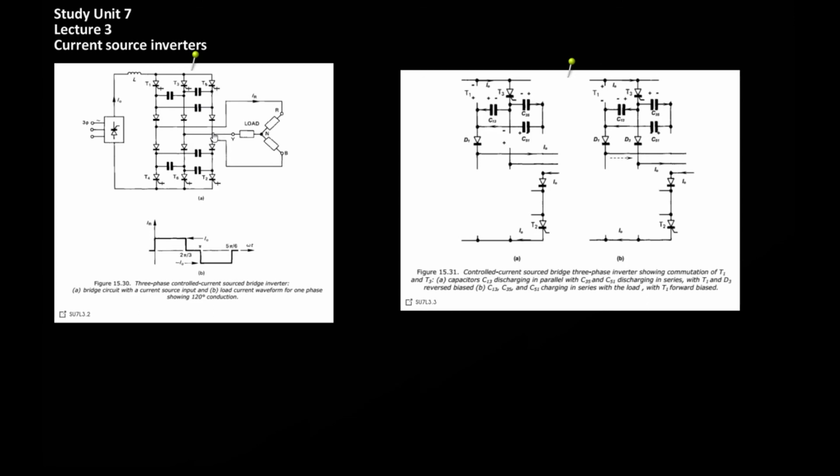A disadvantage of these current source inverters is that their performance is actually quite sluggish, and there can be stability issues if the load current is not high enough. This is because the very low load current will affect the circuit's ability to commutate between switching devices.